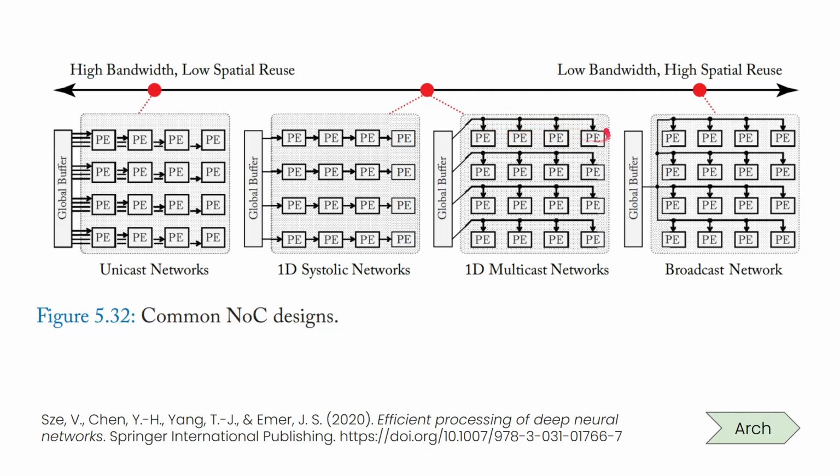Distribute different input activations to the different processing elements, and that allows you to avoid having to spend four cycles sending the different inputs, and then four more cycles sending the same weights to different processing elements. So that's an example of an architectural choice where we change the microarchitecture, we change how things are connected in order to either prioritize bandwidth or spatial reuse. And that depends on the kinds of architectures we want to support, our end requirement.